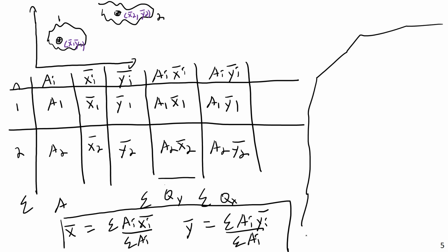And really, that's it. It's really nothing more complex than that. In part 2 of this lecture, we will work through an example or two of this, but essentially that's it. It's just applying this basic tabular method of multiplying distances times areas, and then performing summations of the columns and then divisions as necessary. The only other thing I might mention in this theory video is how to handle holes.